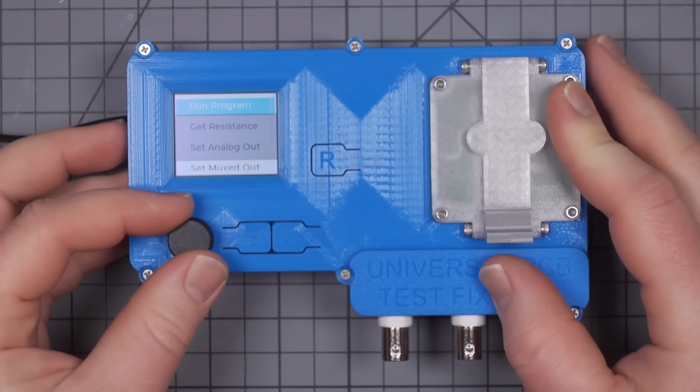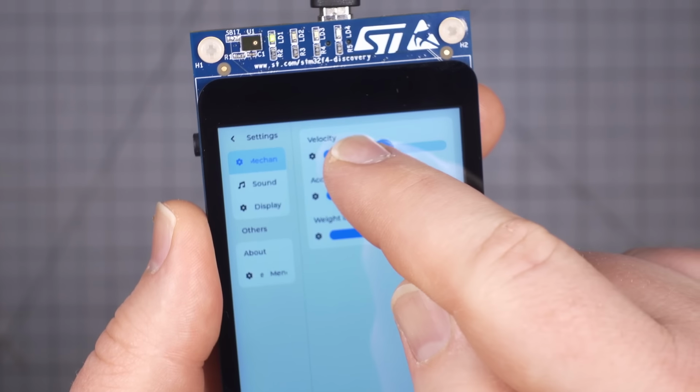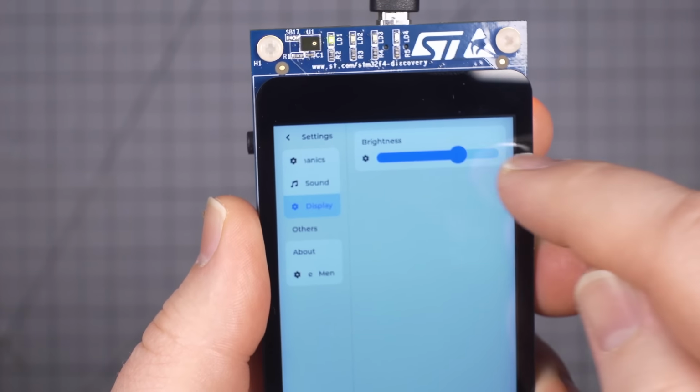The other primary thing these graphics libraries do is provide a mechanism for user interaction with the interface. If you're adding buttons, sliders, or scrollable lists, or whatever, you need some way to manipulate those. The libraries have functionality to tie the movement of an encoder wheel, physical buttons or touchscreens, even mice and keyboards, to movements on the display, and actions such as switching screens or triggering blocks of code. You will generally need to write a small amount of code custom to your hardware to tie the button, touchscreen, or encoder signals to the graphics library, but then the library will take care of the rest.